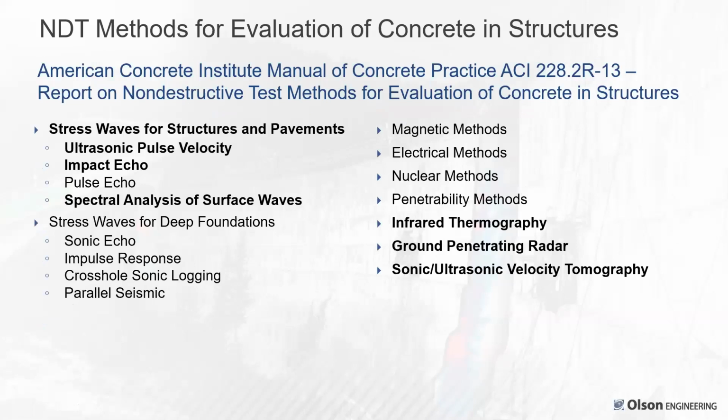The second document that's useful, and almost all the methods we'll be talking about today are discussed in this document, is the 228 report on non-destructive test methods for evaluation of concrete in structures. Again, the bolded methods are the ones that we'll be showing in case histories on the dams today: ultrasonic pulse velocity, impact echo, stress wave methods, surface wave methods, as well as infrared thermography, ground penetrating radar, and some sonic ultrasonic velocity and tomography.